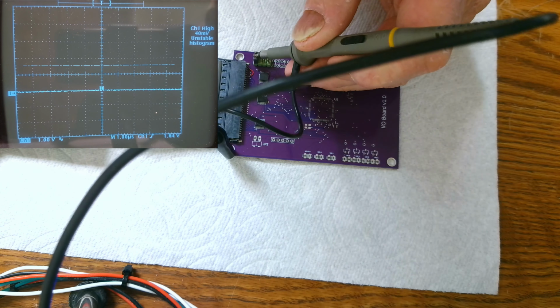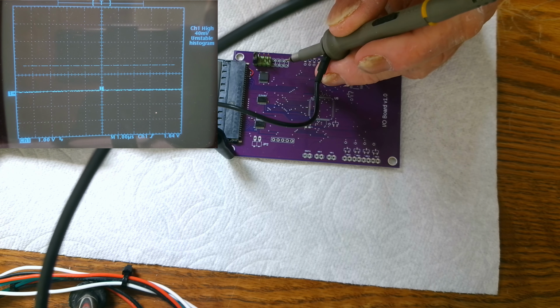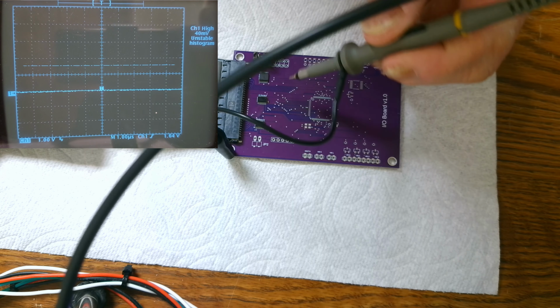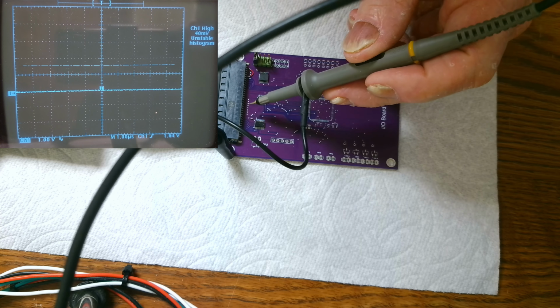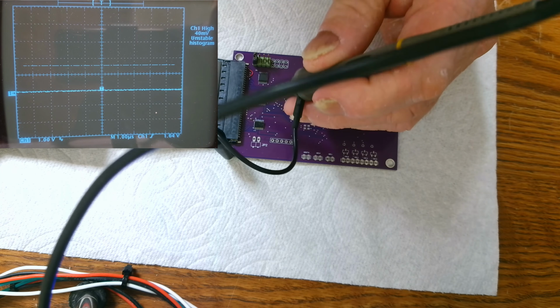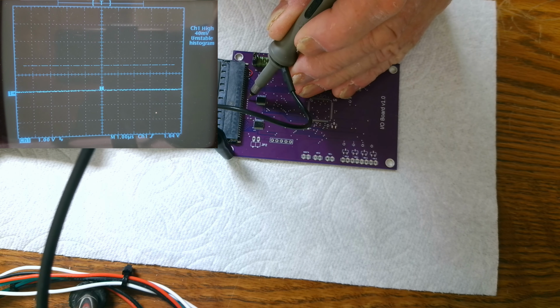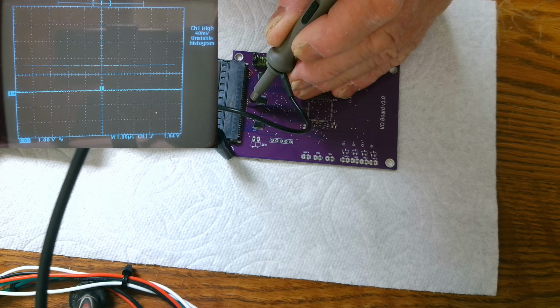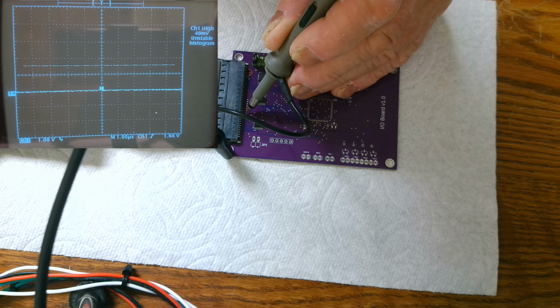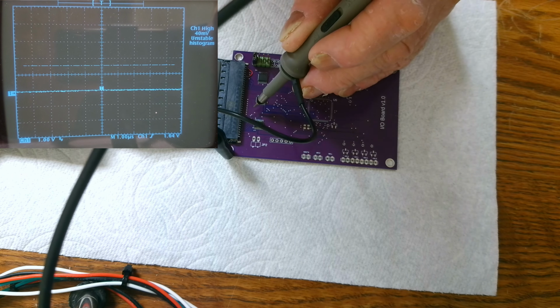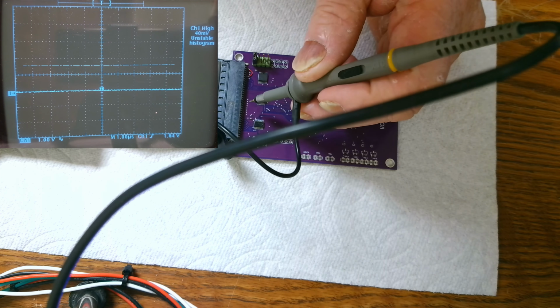So let's jump over to our schematic one more time, and we'll check some. Well, we can check the data lines right here because we know these are from. If you look at the PCB, these are the data lines that switch to the bottom layer and go to that 245 chip.